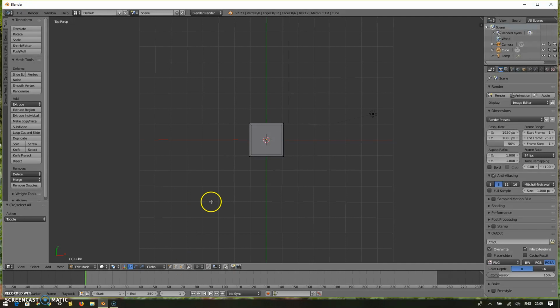Now this is grayed out, which is not enabled. I press B to select this object. Now if I go to the front or right view, you can see the whole object has been selected, right? So you can see that the whole object has been selected, not face wise. So that gives a lot of difference in selection. Suppose you want to edit only one face, it's better to make this enabled.